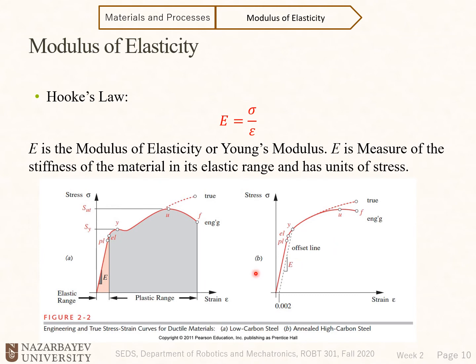But now, briefly, the main difference is that ductile materials have a huge plastic range, but brittle materials don't have a big plastic range. So if they get out of the elastic range, they quickly fail and break. So brittle materials are more rigid. Ductile materials are more flexible.